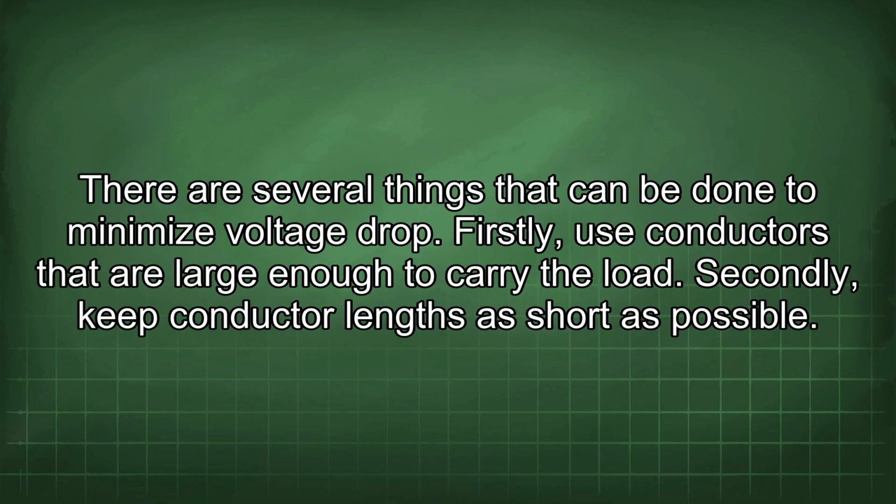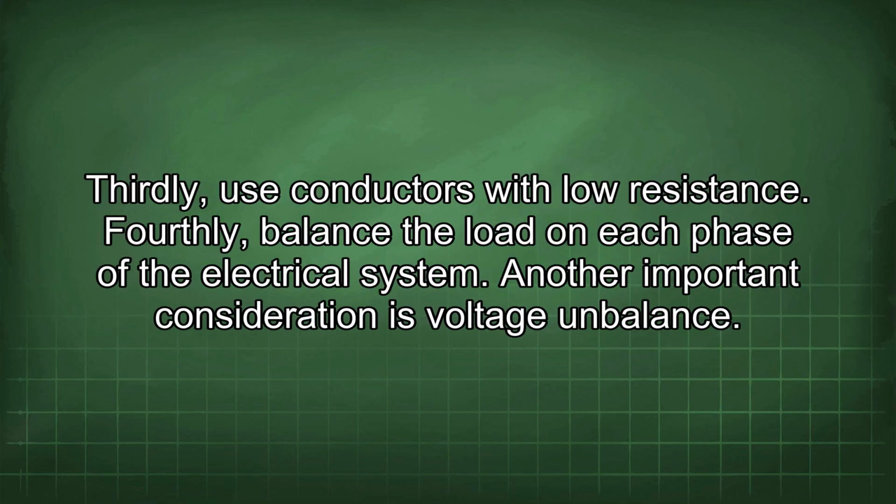There are several things that can be done to minimize voltage drop. Firstly, use conductors that are large enough to carry the load. Secondly, keep conductor lengths as short as possible. Thirdly, use conductors with low resistance. Fourthly, balance the load on each phase of the electrical system.